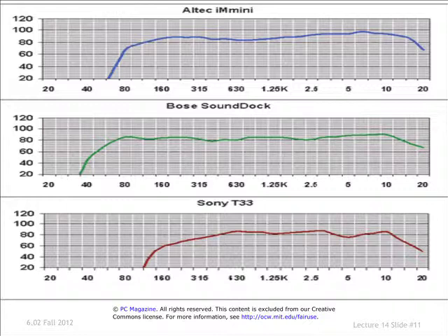In most of these plots, people don't show you the phase. Part of the reason, or maybe the major reason, is that for audio, the ear is not all that sensitive to phase. If we were doing the analogous thing for video, then you'd be very concerned about phase. But in audio characteristics, people will typically only show you the magnitude because the phase distortions aren't picked up quite that readily. Okay, so here's 3 speakers. If you look on the site there, you'll see many more tested.